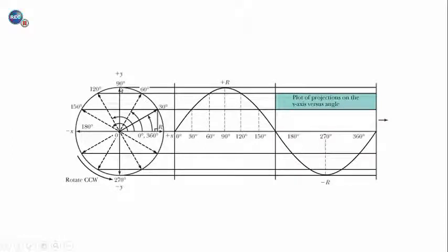But up here at 90 degrees, as the conductor is rotating counterclockwise, and the flux lines are directed down, that's when the conductor is moving perpendicular to the flux lines, and that's when the maximum voltage is going to be induced. So we started off at no volts at 0 degrees. The voltage was increasing up to a maximum value, which occurred at 90 degrees.